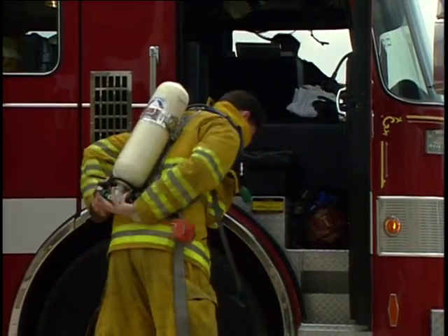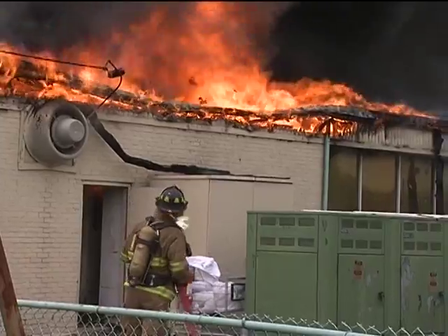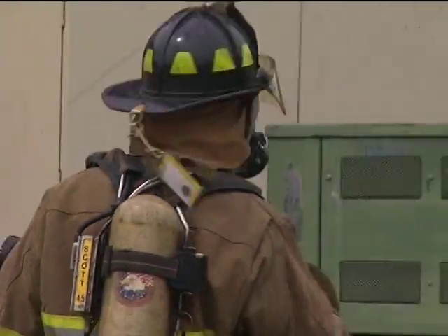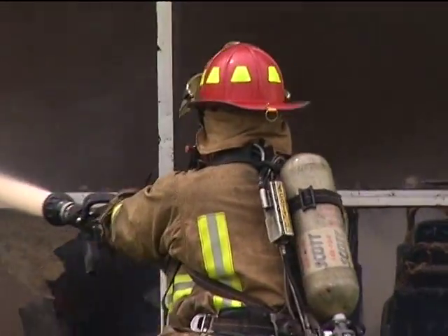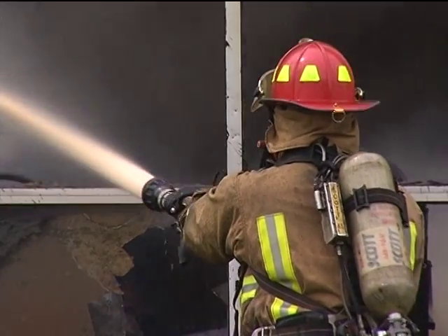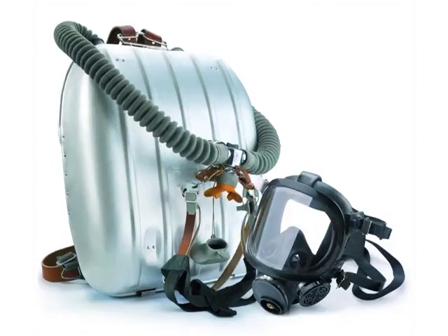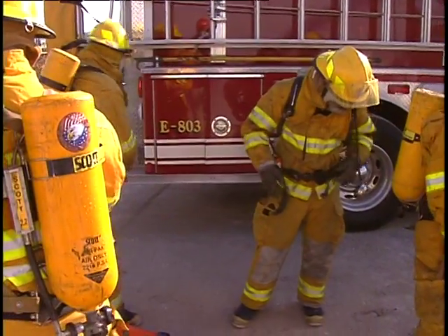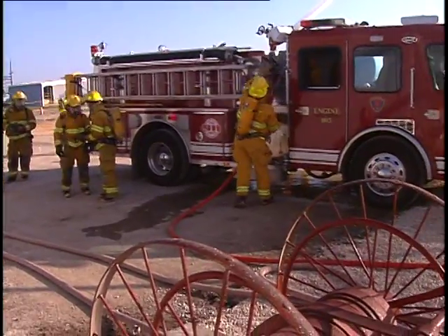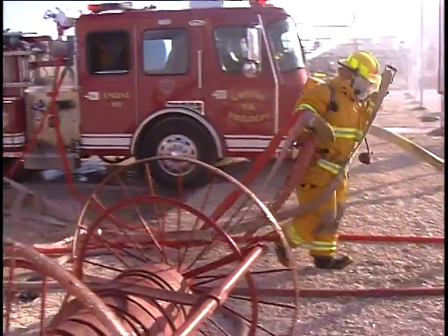A self-contained breathing apparatus, or SCBA, is similar to a scuba tank. The SCBA is commonly used in firefighting and can provide breathing air for an extended period of time. The SCBA consists of a wearable, clean air supply pack and doesn't restrict movement with a hose connection. The closed circuit type can provide breathing air up to 4 hours. The open circuit type only provides air for 30 to 60 minutes. And finally, the SCBA is normally used when there is a short time needed to enter and escape from atmospheres which are or may be immediately dangerous to life and health.